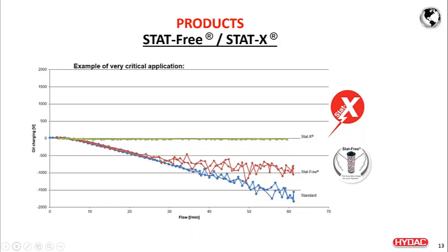And the other key thing you want to observe here is the charging behavior of the oil. The charge in the oil is always negative. As you can see, in the standard element the charge is almost between 1500 to 2000 volts. In stat-free, it is limited to 1000 volts, and in StatX almost null. So that is the key difference we saw when we did the testing to show the different behavior of the elements, and the tendency of charging in the oil when these elements or technologies are employed.